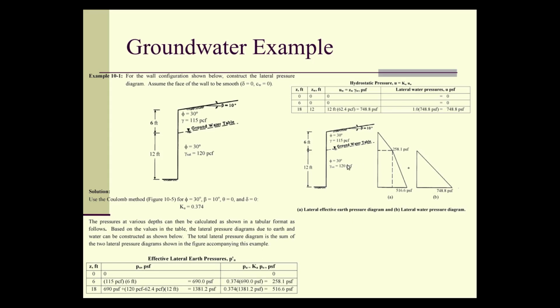So therefore, the forces on the wall are equal to this plus this plus that. And the resultant of that will be a third of the way from the bottom along there. And then those are the total forces we can actually compute. If we know all those, we can actually even compute the moment on the wall at the bottom. And we'll talk about that more in detail when we get into foundations.